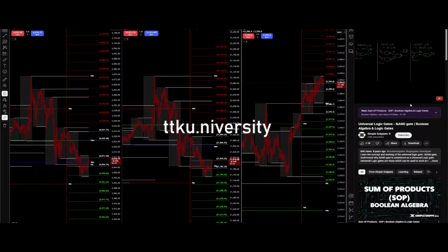Okay, so as you can see, I have divided the screen in 3 parts. In the first part, we'll use a NAND gate and create a NOT gate. So let's get started with the proof. Now we have this NAND gate over here, and we supply an input A 2 times. That is, we supply input over here as well as here, and it's the same input, that is A. So according to the NAND operation or the equation of NAND, we have Y is equal to A and A the whole complement.